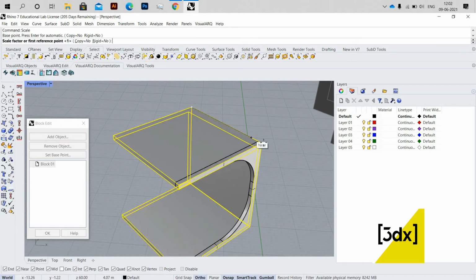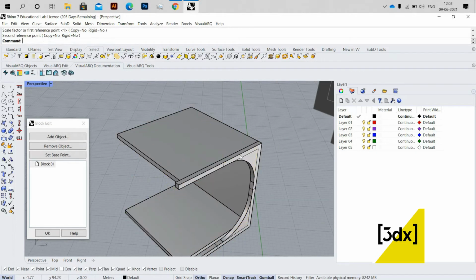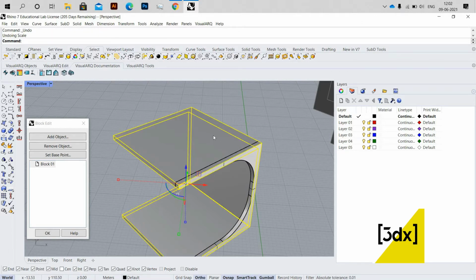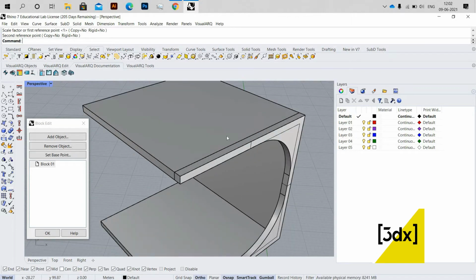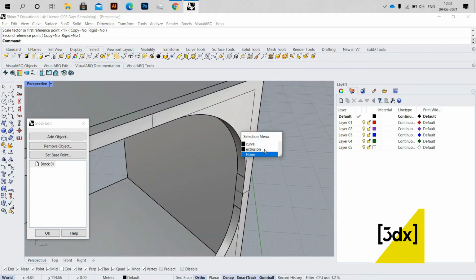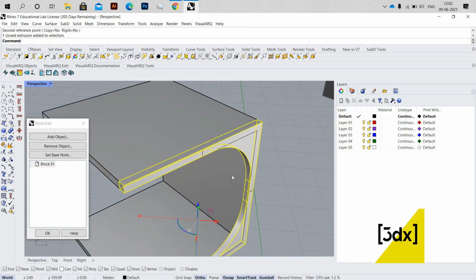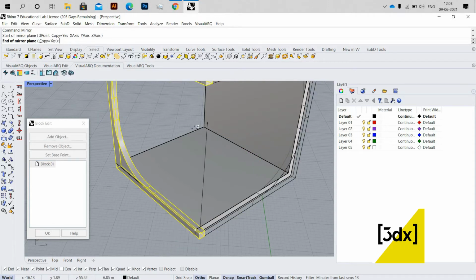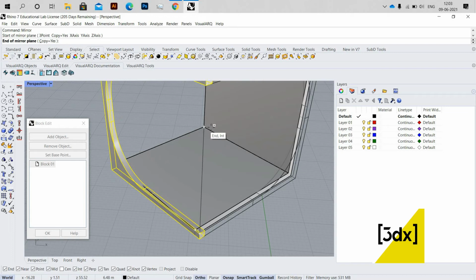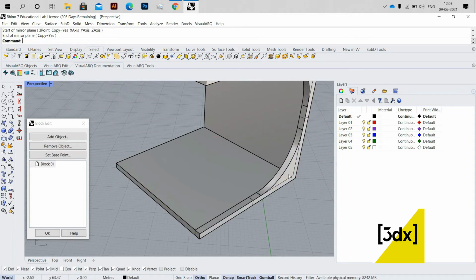So I'm using scale 1D, sorry, I did the scale command, normal scale. So I'm using scale 1D. Scale 1D is a command where I can scale in only one axis. So I'm bringing the solid which is overlapped with the facade by help of scale 1D. Now I'm selecting the facade. I'm using the mirror command. I think it comes perfect. Mirror command will work now.